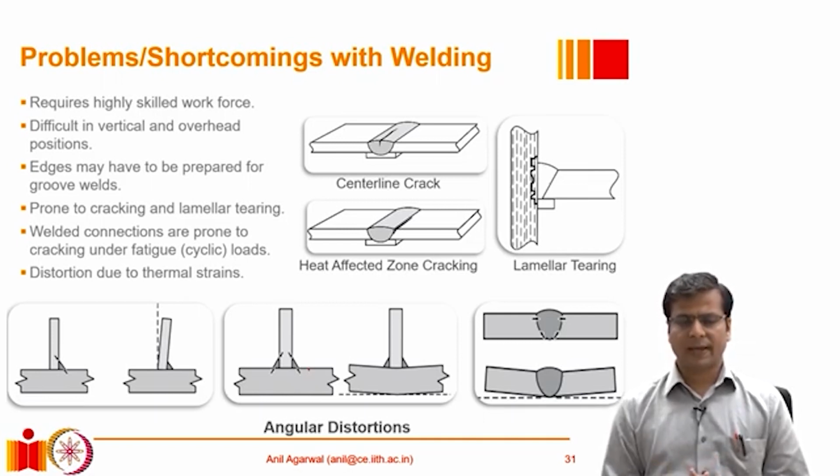Welding also requires edges to be prepared, especially if you are going for groove welds. Groove welds are quite common, especially in the case of splicing. In such a situation, we need to spend a lot of time and cost on developing the edges, which is basically removal of the material, and then again we have to fill that with the welding material.